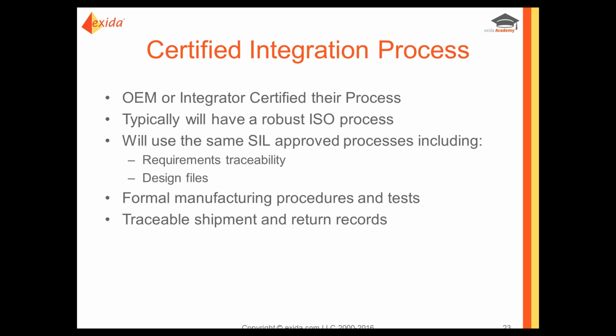A more pragmatic approach, which gives pretty much the same benefit as a certified assembly but is more practical, would be to extend certification not just to valve design or actuator design, but to include the integration process, because many OEMs integrate actuators and devices in their factory on orders. They don't do it all the time, obviously, but if a customer orders an integrated assembly, they'll do that.